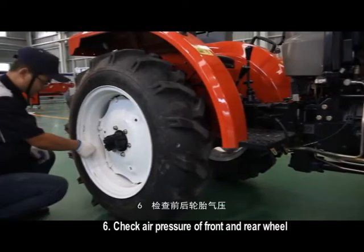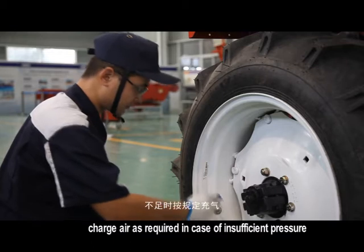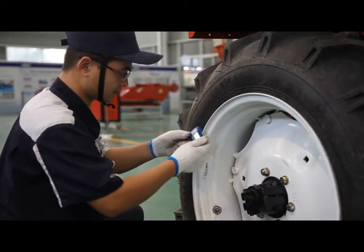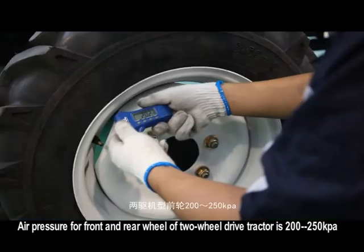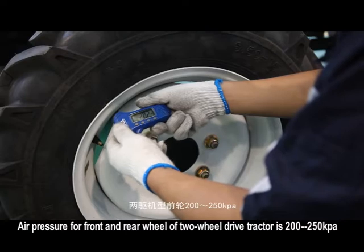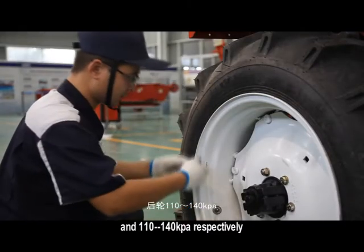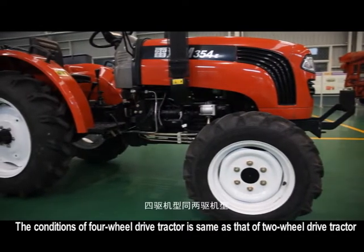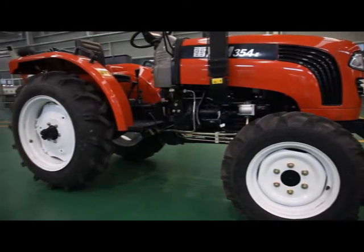6. Check air pressure of front and rear wheels. Charge air as required in case of insufficient pressure. Air pressure for front and rear wheels of a 2-wheel drive tractor is 200-250 kPa and 110-140 kPa respectively. The conditions of a 4-wheel drive tractor are the same as those of a 2-wheel drive tractor.